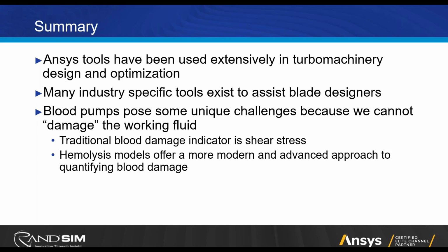Traditionally, the industry has used shear stress pretty much exclusively to predict blood damage, but we have learned in recent years that hemolysis models are more accurate and give us a better look at the true damage that may be occurring in these devices, so that we can do a better job of mitigating it.